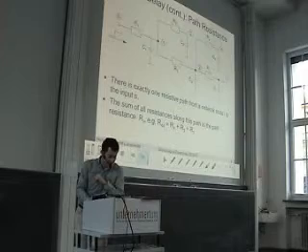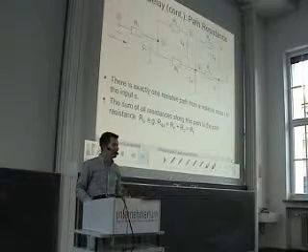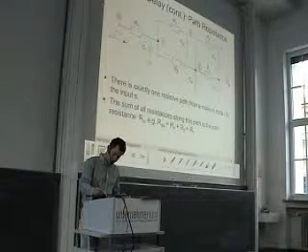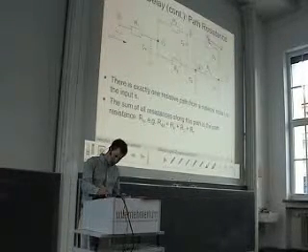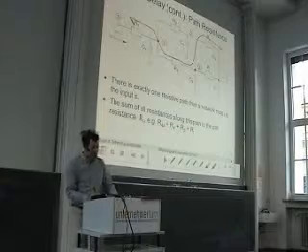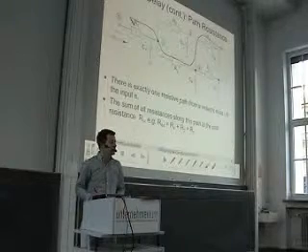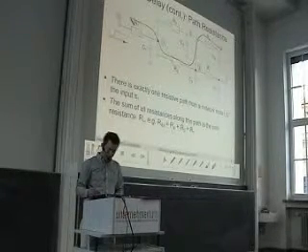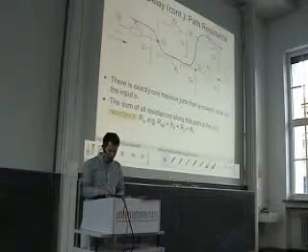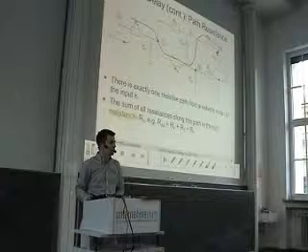And if this is the case, then we always have exactly one path from each node back to the input. So for instance, if we go from this node to the input, you can see there is exactly one path from the node to the input. And the sum of all resistors that we pass along this path is called the path resistance. So the path resistance is the sum of all resistors on our way from the input to the node under consideration.